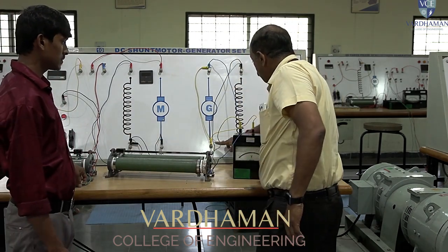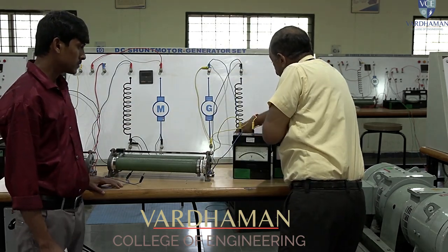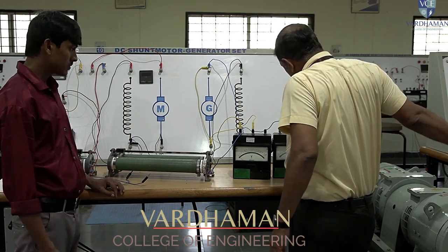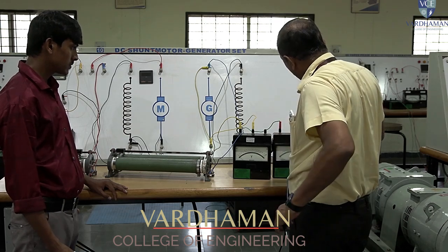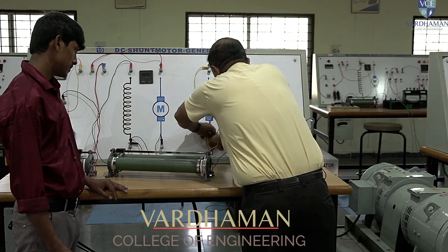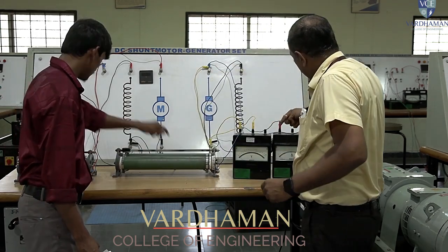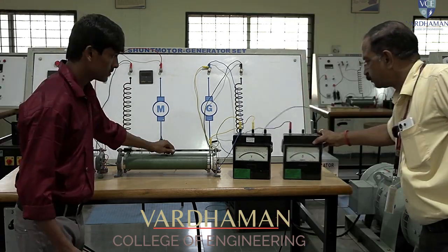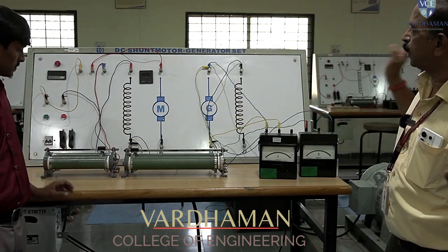And then this is to be closed. I want to measure the field current, how much current I am going to apply in the magnetic field, so I will connect an ammeter here. Since the range of this excitation current is 0.48, I need not go for two terminals; I will connect it to one terminal only. This is closed at the armature, AA. As shown in the circuit diagram, it is very clear that ZZ is connected to the ammeter, and the ammeter's other terminal is taken to AA. Thus the circuit is closed. So this is about the connection diagram.